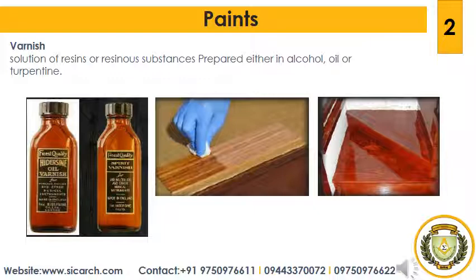The next is spirit varnishes. The methylated spirits of wine are used as solvent in this type of varnish. The resins are of soft variety such as lac or shellac, and the spirit varnishes dry quickly. But they are not durable and are easily affected by weathering actions. They are generally used for furniture. The French polish is one type of this, the finest finish for ornamental furniture prepared from the superior quality of wood. The French polish is a variety of this class of varnish and the desired coloring tinge can be obtained by the addition of suitable coloring pigment.